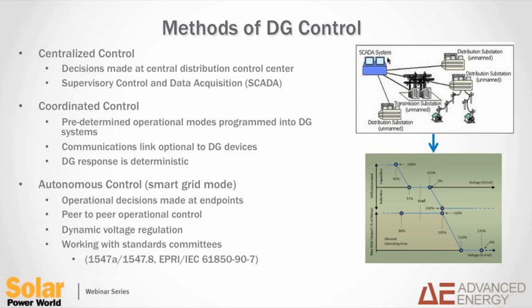But in the distribution network, you're probably looking a little bit farther down the list, where more coordinated control is needed, where they can perform studies in the back office and understand what inverters should be doing at different times of the day from a reactive power or power factor point of view, so that they're not imposing additional voltage excursions, all the way down to autonomous control, where the inverter can monitor voltage out on the network and control itself accordingly in a very autonomous fashion.